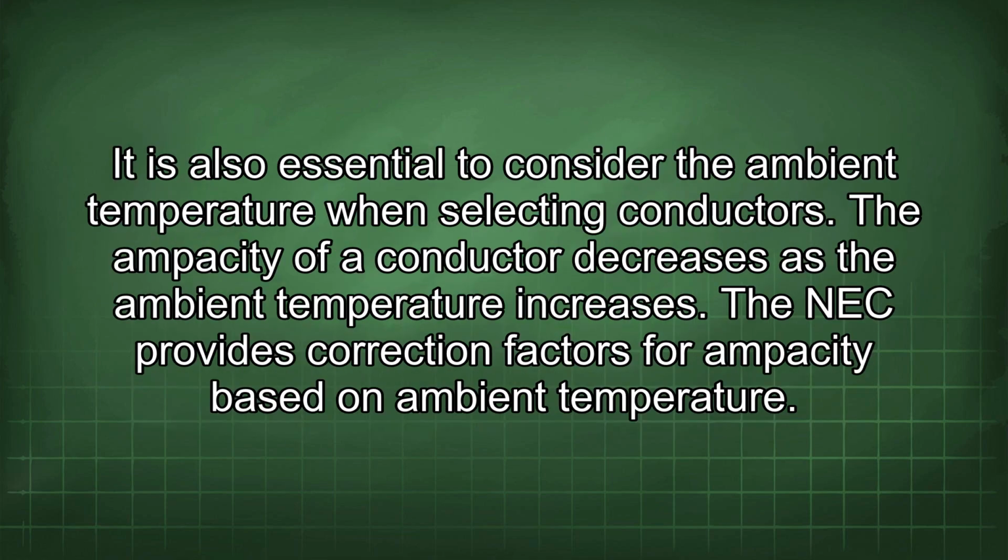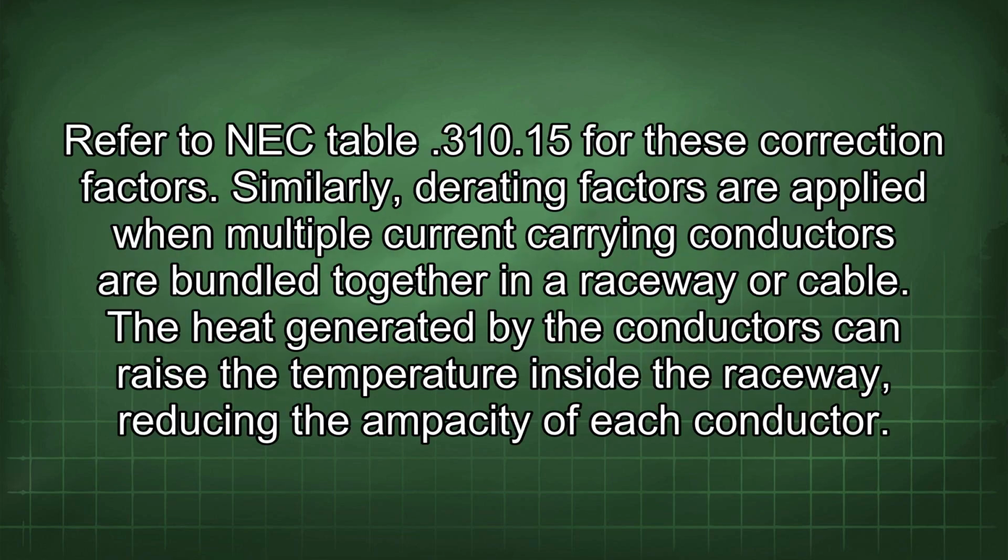It is also essential to consider the ambient temperature when selecting conductors. The ampacity of a conductor decreases as the ambient temperature increases. The NEC provides correction factors for ampacity based on ambient temperature. Refer to NEC Table 310.15 for these correction factors.